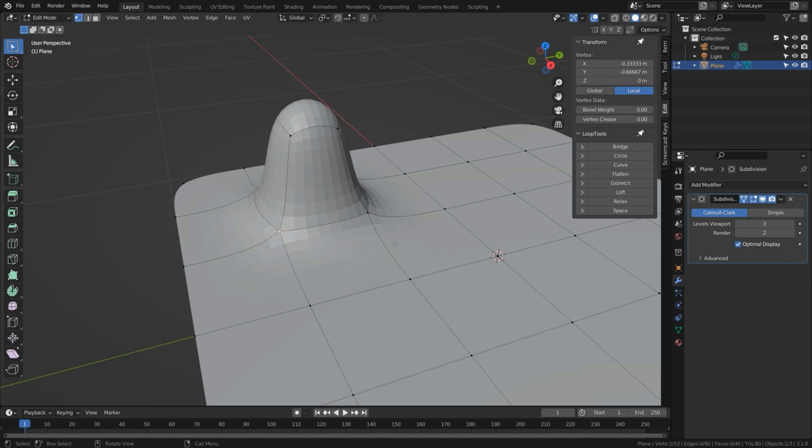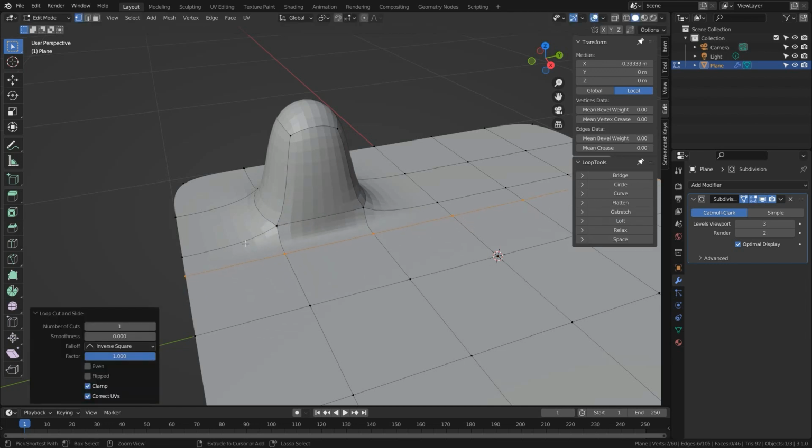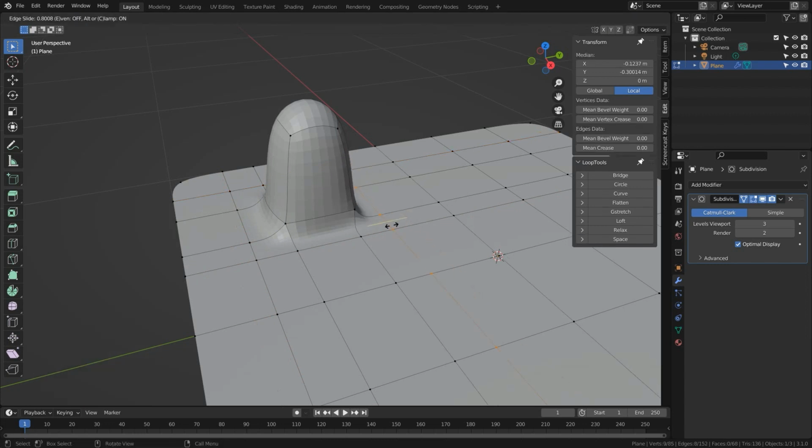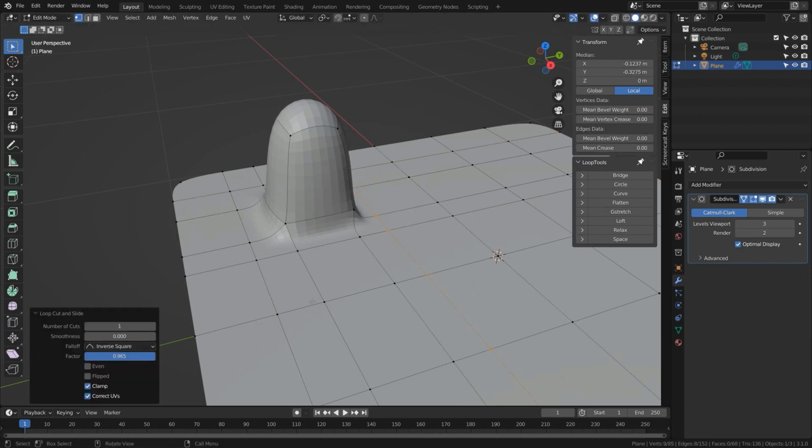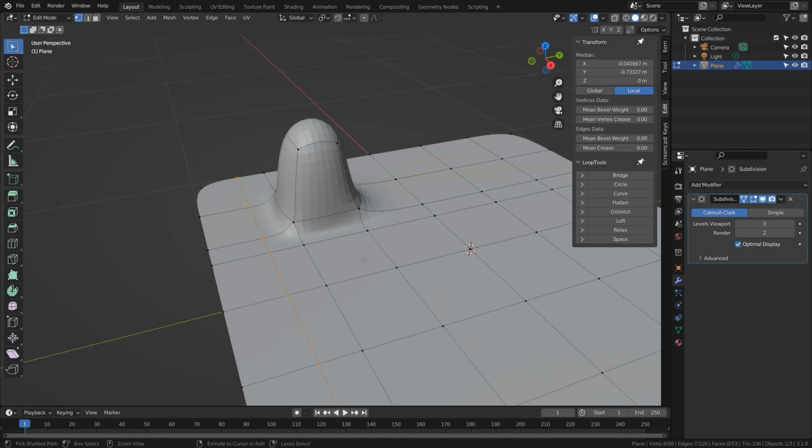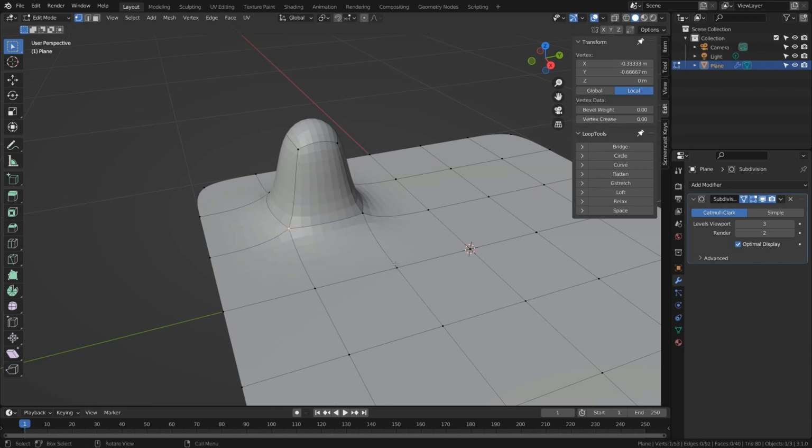If we want to control the softness of the curvature into the shape, we have to add loops which are flung across the entire mesh, affecting the shape of anything in their way, and this can be very problematic. You'll see that if I add these loops here to control the curvature into the shape, that we have these 4 loops which spread across our entire surface, and when you have a big complex surface to model on, this is a real problem. They all need to be adjusted individually to control what should be a single aspect of curvature. Let me just undo a few times to get rid of those. They're no good to us at all.